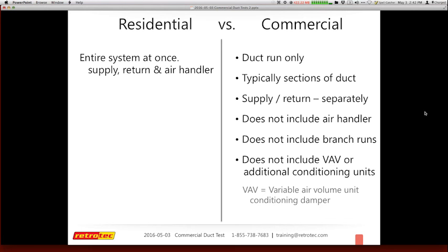So I only have to do the transverse joints only, right? Here we also added the longitudinal seams and all the penetrations that go along with that. So C class is a very leaky system, right? And it also tells you what my leakage class is based upon these columns that are moving straight up and down.